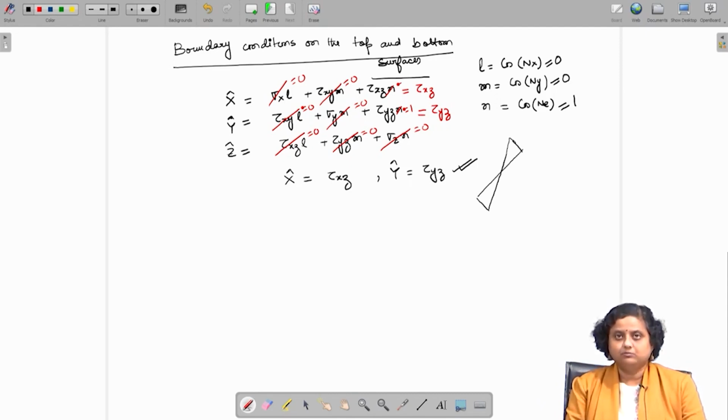giving rise to only a torsional moment. But it is not that straightforward for a non-circular cross section shaft, where there is not this form of symmetry which exists for a circular cross section of shaft. So, it is not obvious that the resultant x hat and y hat, because of the distribution similar to the shear stresses, will be equal to 0.